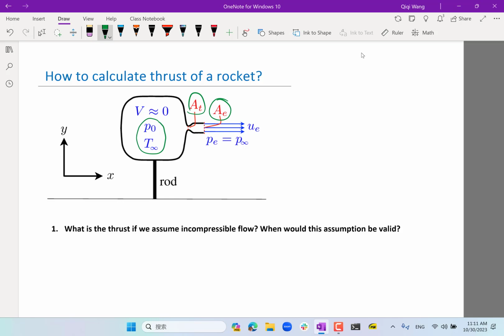Right. So basically, we have this rod holding this whole thing at a steady state. The question is, if we put a load cell on the rod, how much force would we measure? We can just use density times area times air velocity at the exit, right? So what principle are you using to assert that? Conservation of momentum, that's right.